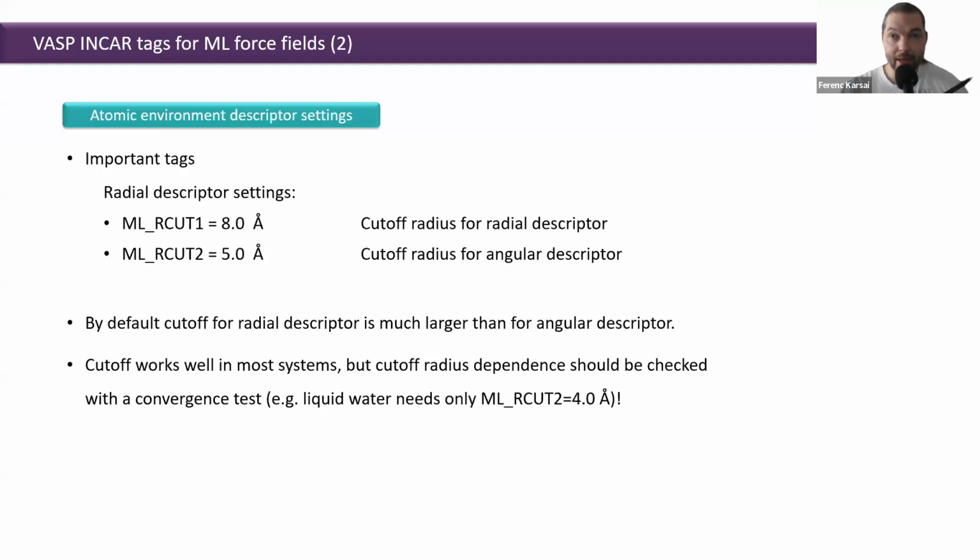So it really depends on the case, the convergence study with respect to that. You wouldn't continuously increase it and have it become continuously better. In this case, having a smaller cutoff radius is better than the default 5. The reason it doesn't get better with increasing radius is that you would need more training data.